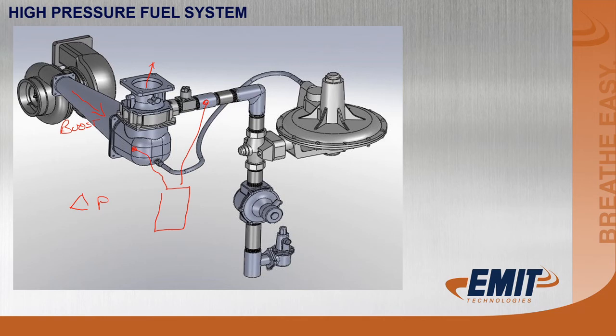We always want to measure this delta P between the manifold and the fuel pressure. The reason being, we always have to maintain 5 inches fuel over air. That's the only way that fuel is going to get in the carburetor, is if it's 5 inches above. So if we're running something with 15 pounds of boost, our actual fuel pressure going into this is going to be 15 pounds plus 5 inches of water column.